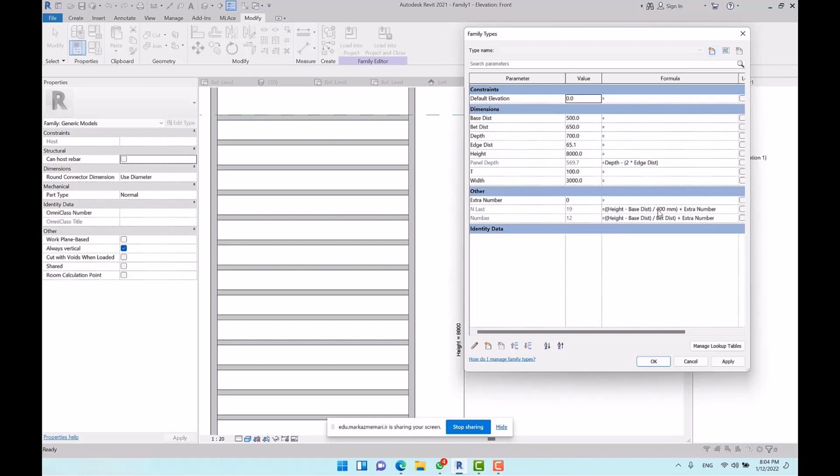This parameter as an integer type gives us rounded values. For instance, 18.8 is rounded up, and 18.1 will be rounded to 18. So if it is rounded to the lower value, it increases the distance between the panels, for instance by more than 40 centimeters. But if it is rounded to the higher value, it decreases the distance between the panels.